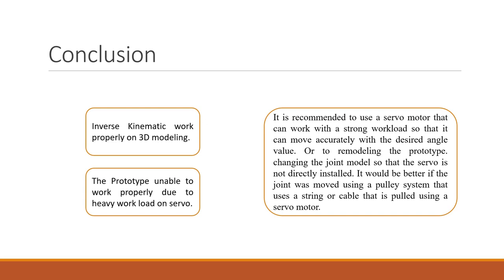After these experiments, we conclude that the inverse kinematic can work properly on the 3D modeling, but unfortunately, the prototype is unable to work properly due to the heavy workload on the servo. Therefore, we recommend using a servo motor that can work with a strong workload so that it can move accurately with the desired angle value.